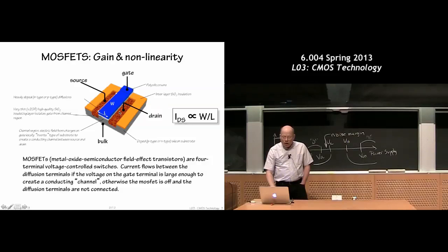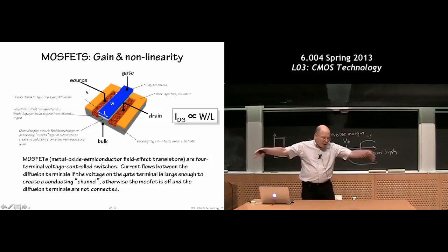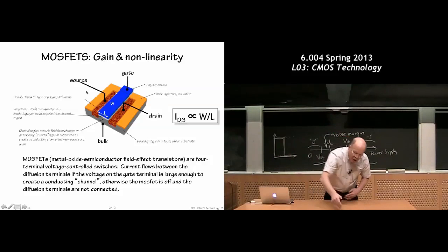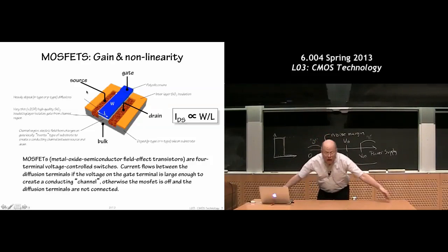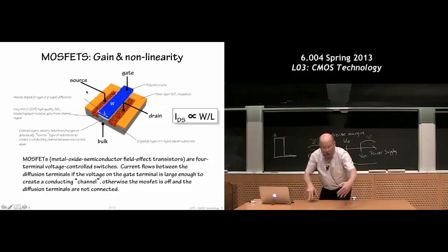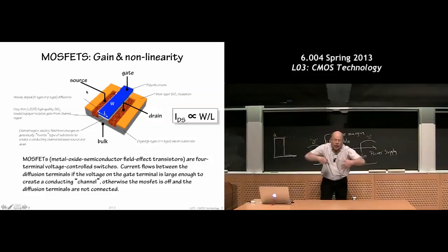And so the current flows across the length. If this is width and this is length, I'm the source and you guys are the drain, the current will be going whoosh this way, across the width of the device, all the way across the length. So the electrons are flowing from you towards me. You're the drain, I'm the source, and the gate is covering this table here.